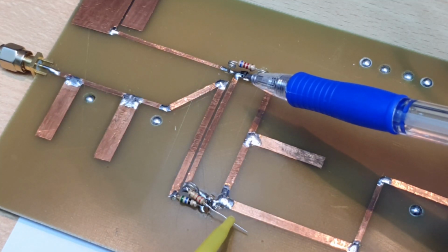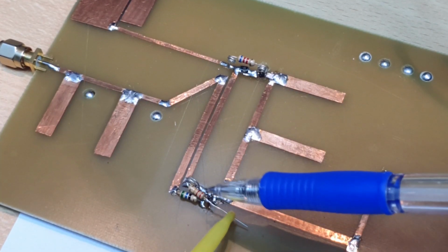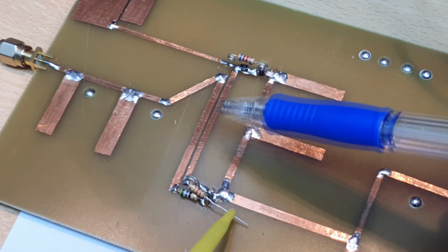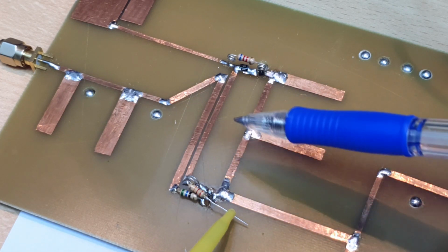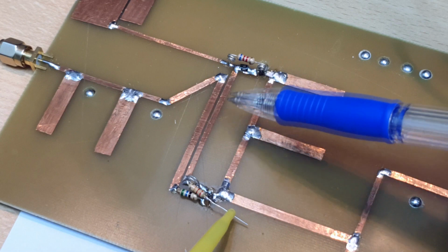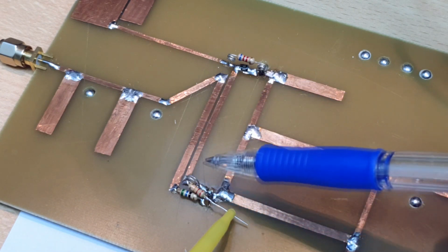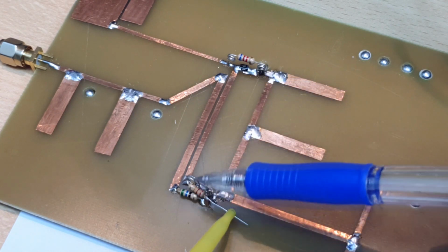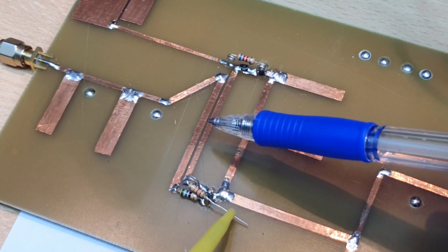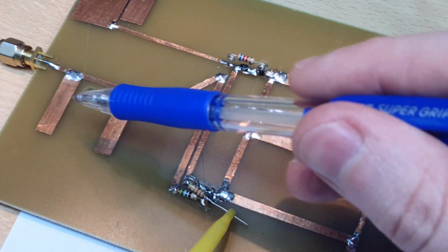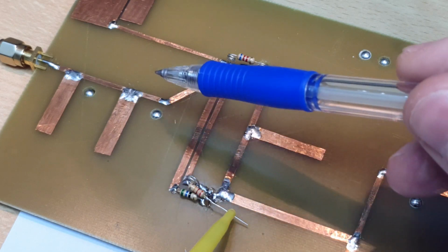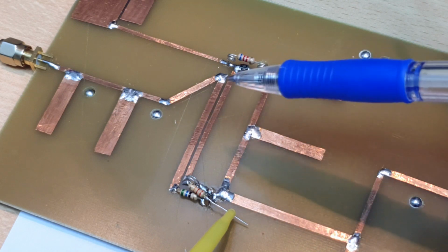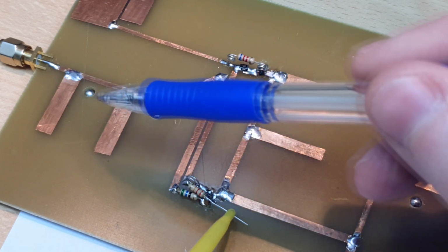The output of the amplifier here is fed back to the mixer with this transmission line. So this is the closed loop we saw on the block diagram. Only a small fraction of the amplifier power is coupled to the output with this directional coupler. So of the power traveling from the amplifier to the mixer, part is coupled with this coupler and goes to the output connector. I also placed here at the output a trap at the input frequency to prevent any leakage of the input frequency, 1.6 GHz, from going to the output.